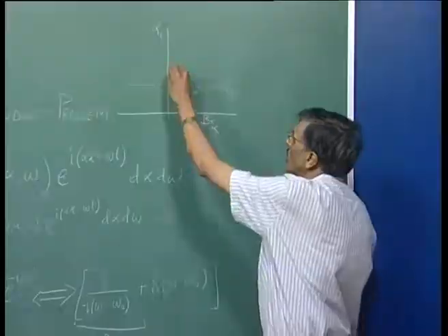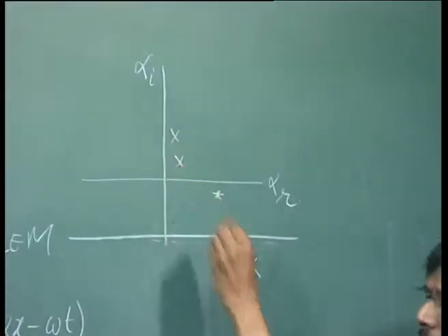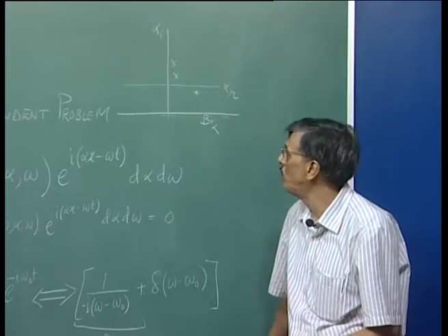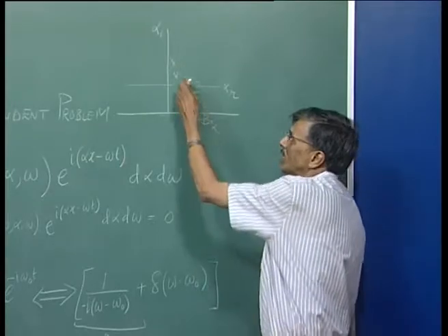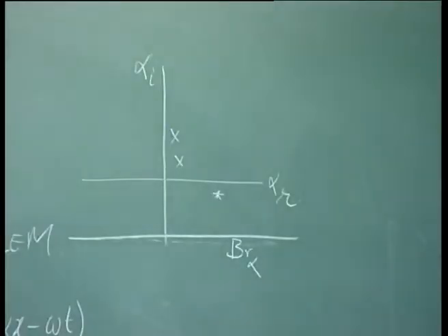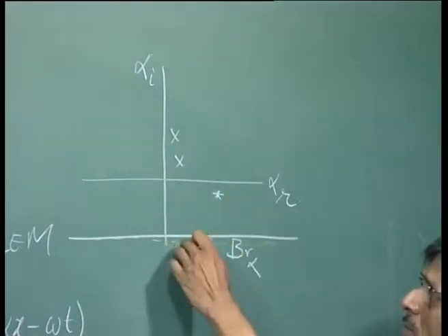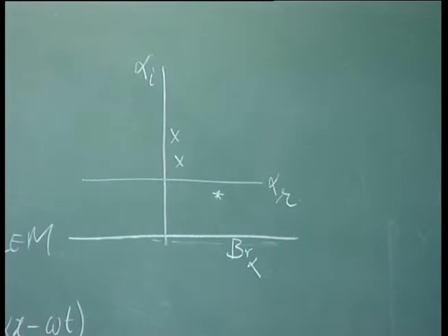Once you have gotten all the eigenvalues, let us say in the last case when we looked at Reynolds number of 1000 and omega naught equal to 0.1, we found 3 such eigenvalues, right. That is what we found. Now, we need to really put our Bromwich contour below all of these 3.